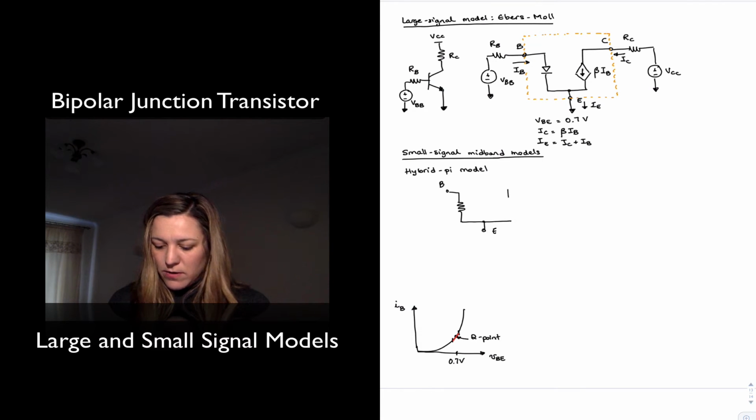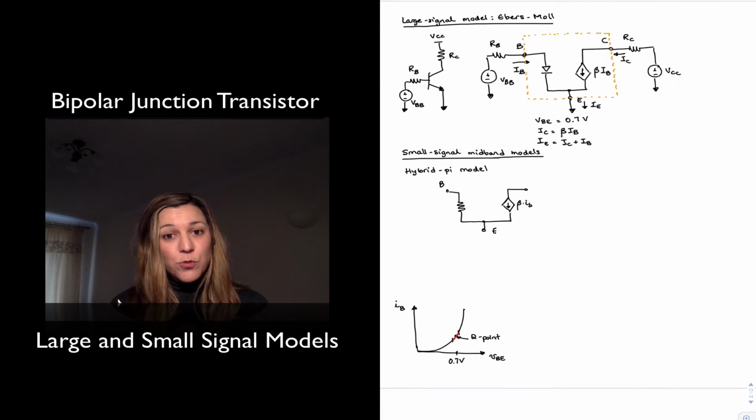And then in the case of the collector to emitter terminal, we still have that current source, which we're going to represent in terms of the transconductance. And that's just for convenience. We could say this is equal still to beta times IB, except it will be beta times small ib now, because we're talking about the small AC signals. This resistor we're going to call R pi. We're going to see in a second why.